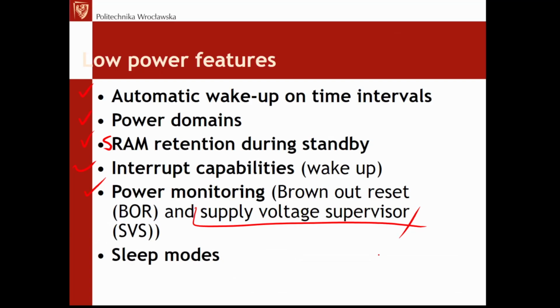First of all, to inform a core that supply voltage is getting to dangerous values. Second of all, it is to shut down automatically the microcontroller when the supply voltage gets below some threshold, in order to prevent malfunctioning or false operation of a microcontroller.